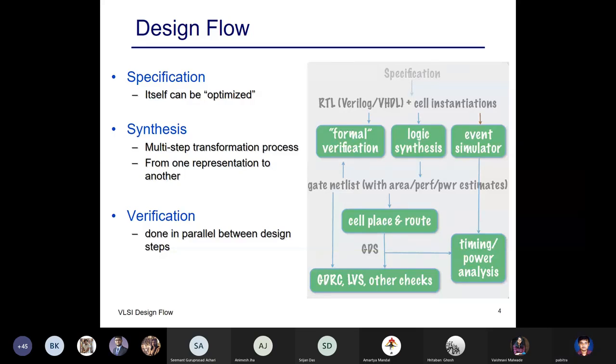So if you have written a Verilog description of a hardware, you have compiled it, and then you have a test bench, which is again a Verilog program. Unlike normal software where input test cases are just user inputs, here the test inputs are also written in the form of a Verilog program. So this test input plus the program, if you give to the simulator, it will give you the output.